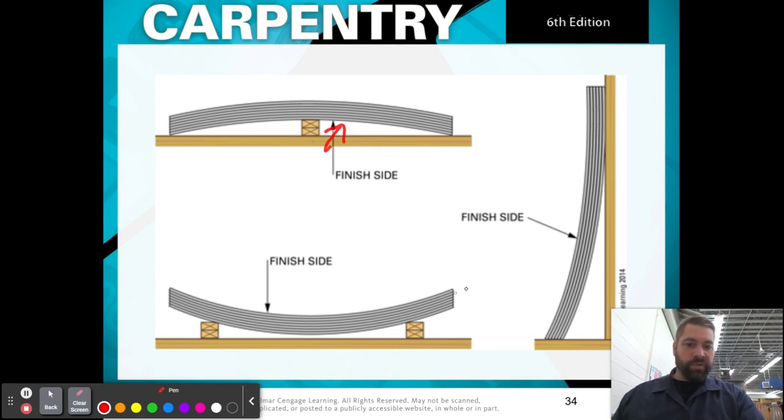This is another way of doing it. And of course, you can line them up against the wall. So this is a good time to say, this is how you don't put your dunnage for your drywall. So you can see in this instance, if we want to keep it straight, we'd want to put more here. And that's better than having it like this, because if you want to curve it on purpose, that's one thing. But if you're curving it by accident, that creates another issue altogether.